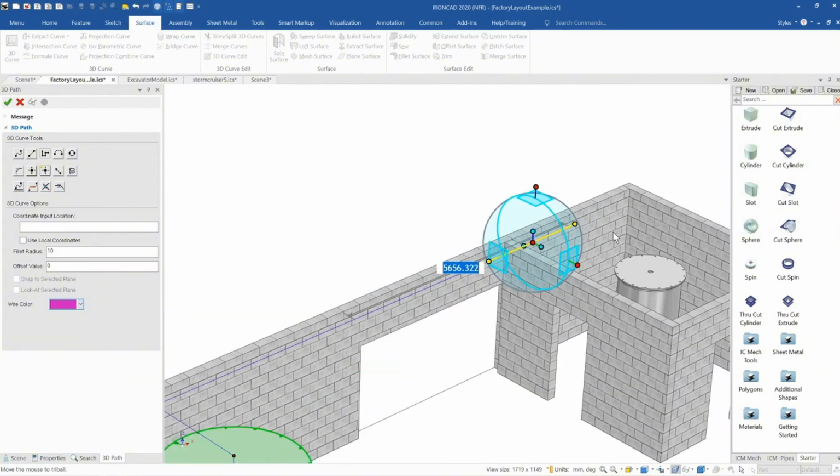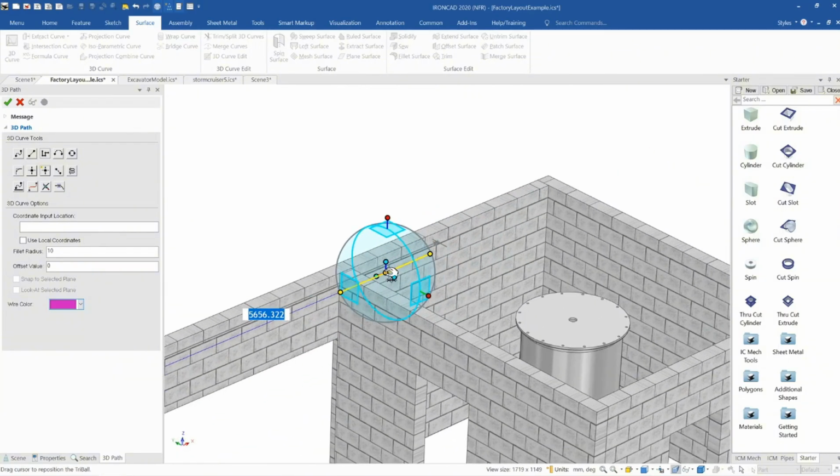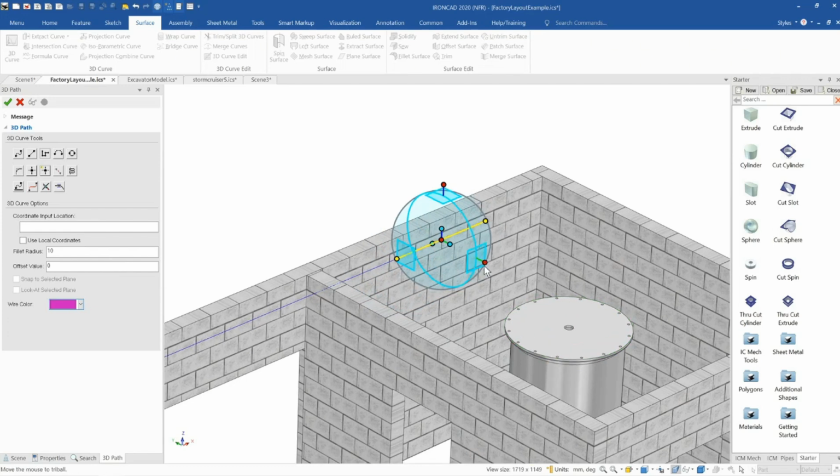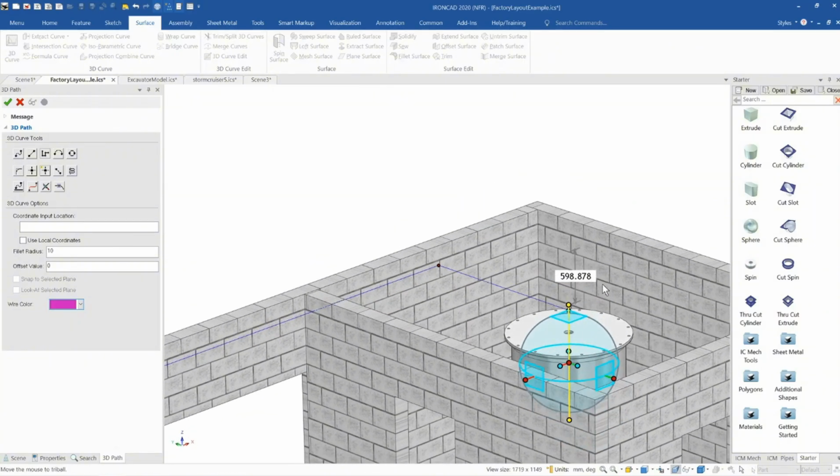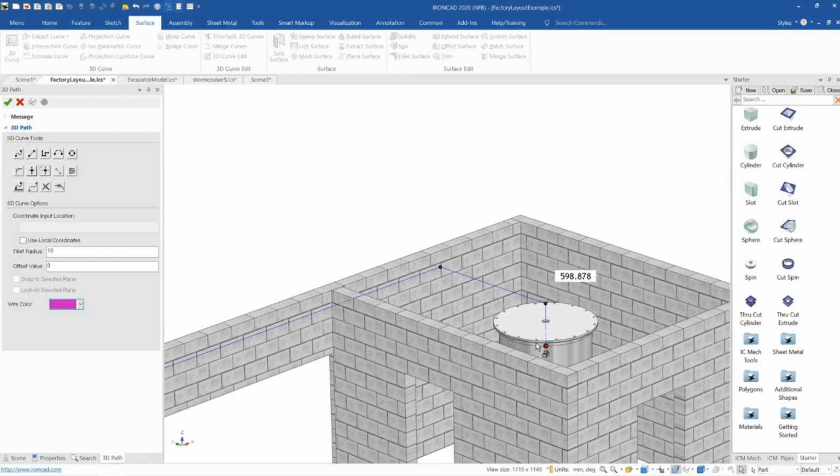all the way across here. And I'm going to go from here, so we're locked on that axis. I'm going to align to the center point of this, hold down the shift key to get that center point snap. Press the P key again there, then I'm going to lock down this axis and go across to the center point, press the P key again there, and then drive that down, and I'll just go further down than the top in this case and just press the P key again. Now I'll hit the escape key to finish that off.